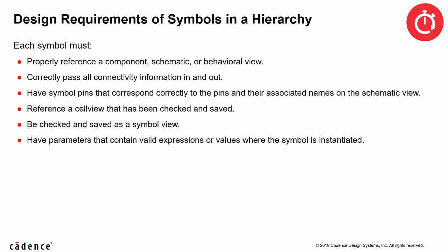So there are some design requirements that must be met before you use symbols in a hierarchy. Each symbol must properly reference a component, schematic, or behavioral view. It should correctly pass all connectivity information in and out. It must have symbol pins that correspond correctly to the pins and their associated names on the schematic view.